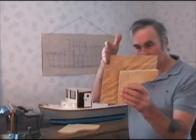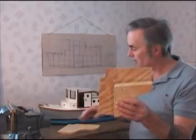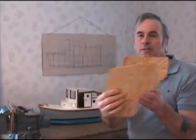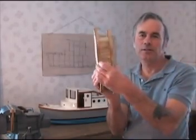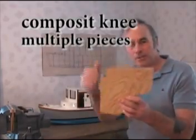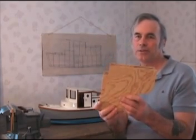This is cut for a stringer, a cabin top stringer that runs along here. These two gussets will form a very strong composite knee. It's where two pieces come together, to strengthen and support the joint between two framing pieces.